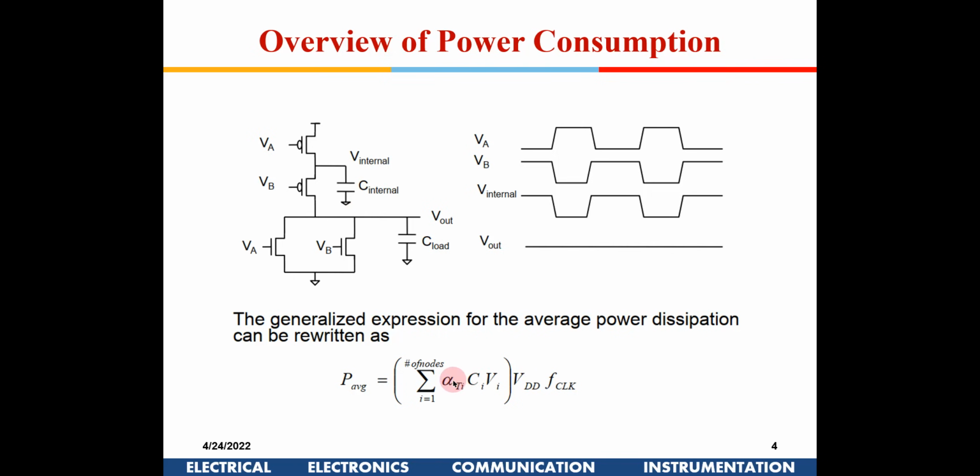So accordingly, you have to put that activity and summation of the voltage out here, and this voltage need not go to full VDD, right? Normally it might, but from circuit to circuit it might differ. That is why we have written CI and VI out here, and the corresponding activity factor. Okay, so this is the more generalized form of power for any CMOS circuit.